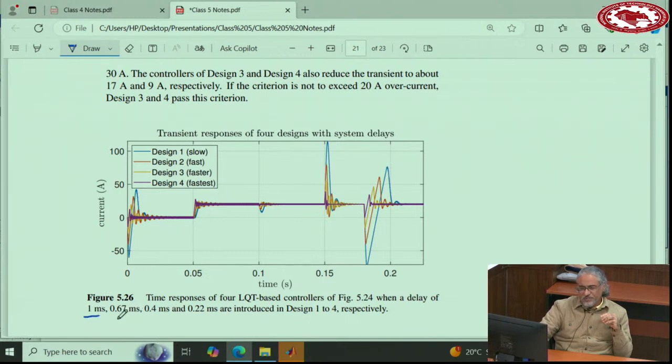Yeah, the delay margin that I said. Now, I intentionally went to the simulation and inserted a delay in the control loop, and that delay models the delays of the digital control, because the controllers and simulations you see here are in continuous time, since these are easier to design and simulate. I did not use digital control. So whenever you want to include the delay of digital control, you need to insert a delay yourself.